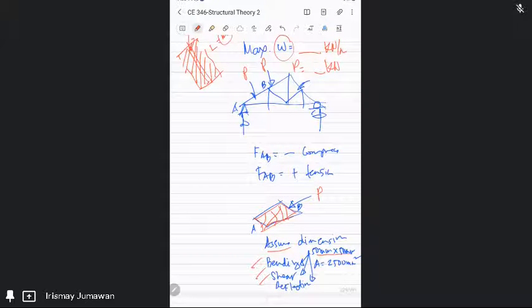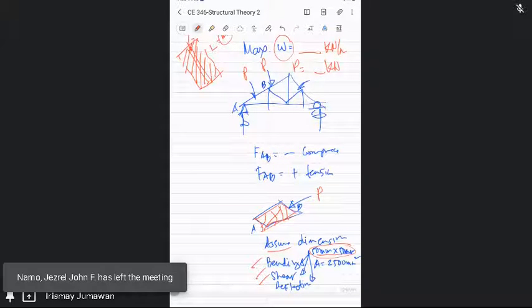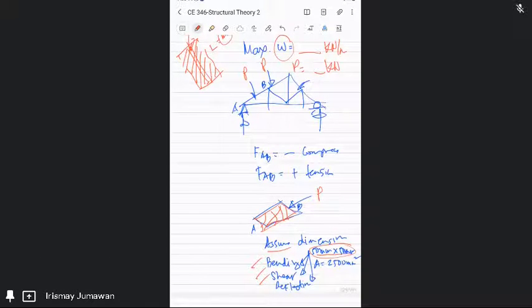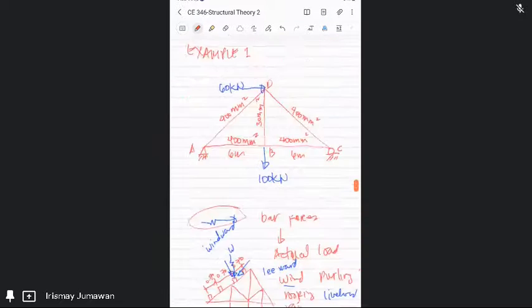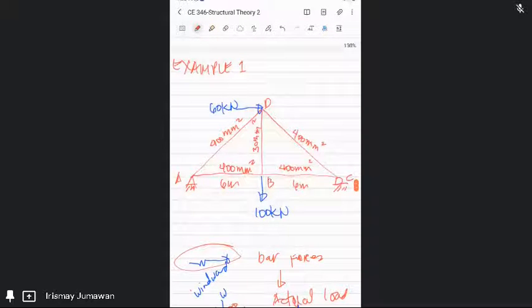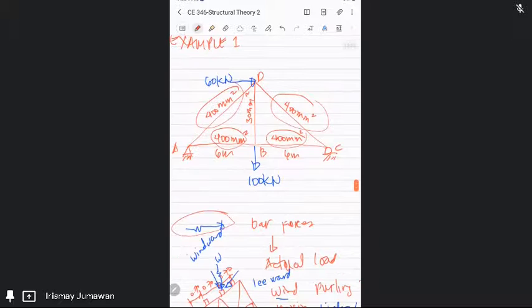You conclude this for the diagonal member, the top chord, and the bottom chord, using the actual load on each member. That gives the dimension of your members for shear and bending, and then you check deflection.